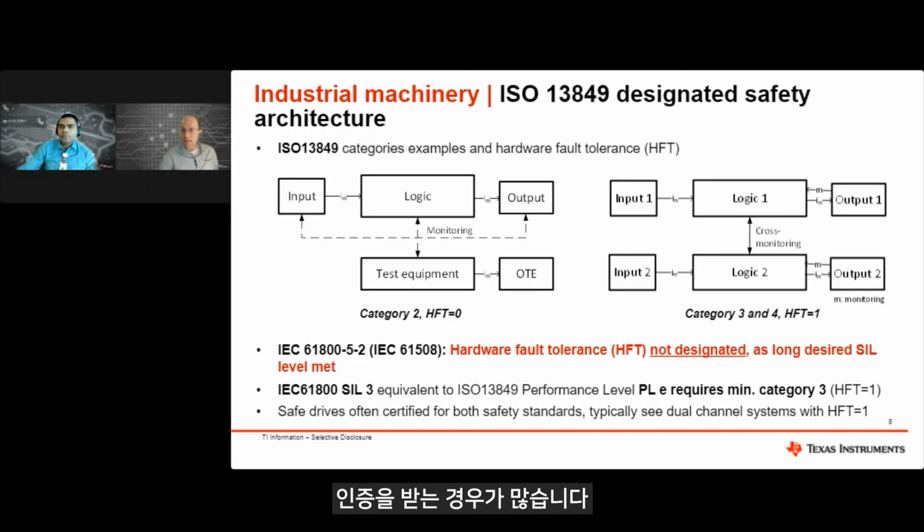Let's have a closer look into the STO1 load switch subsystem. We can see here we have a 20-volt STO input. So we have an isolated input receiver, which then turns off the load switch in case of an STO. And this load switch removes power from our CMOS input isolated gate driver. What about failure modes of these semiconductors? Where do we get this information on failure modes?